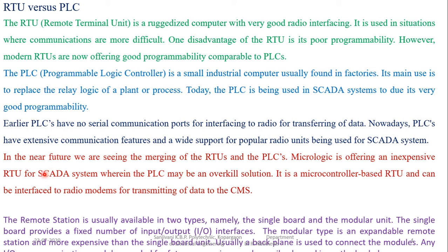Micrologic is offering an inexpensive RTU for SCADA systems, wherein the PLC may be an overkill solution. So basically, Micrologic is now offering extensive RTU solutions. Allen Bradley product is that. But over a period of time, the PLC will give a better solution. It is a microcontroller-based RTU and can be interfaced to a radio modem for transmitting data to the central management monitoring system. Now, the RTUs are of two types, single board as well as modular unit.